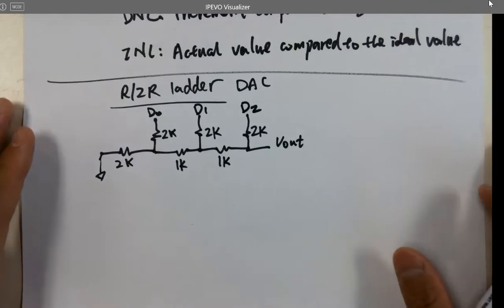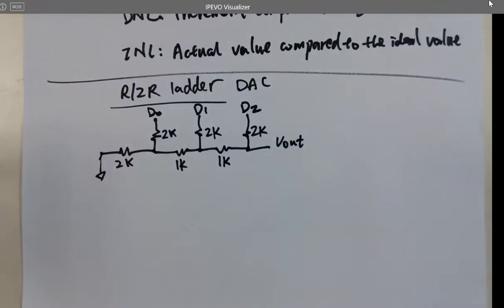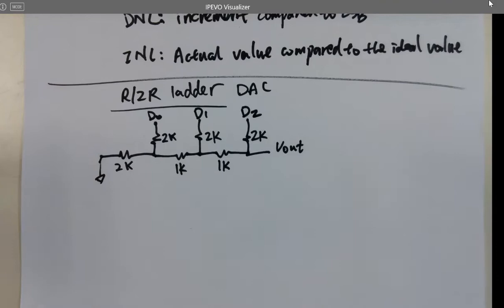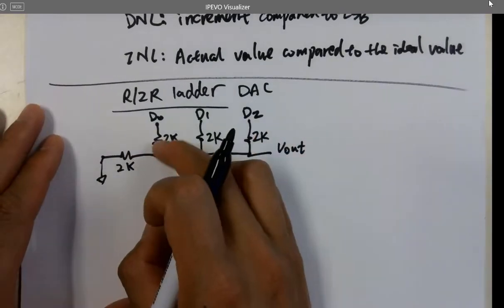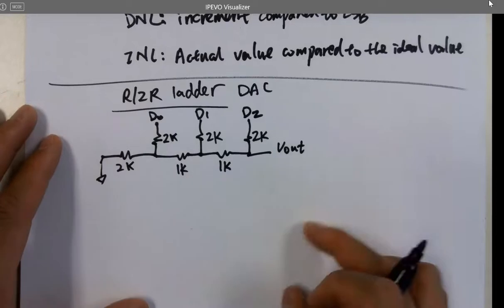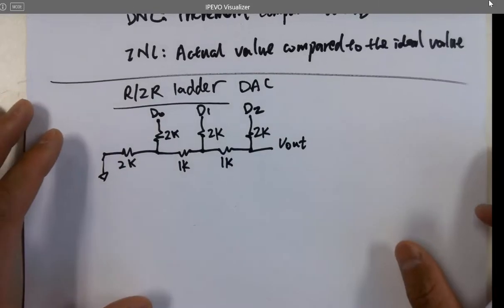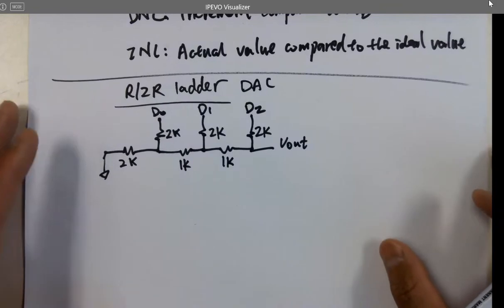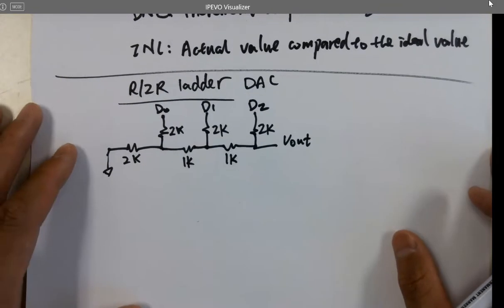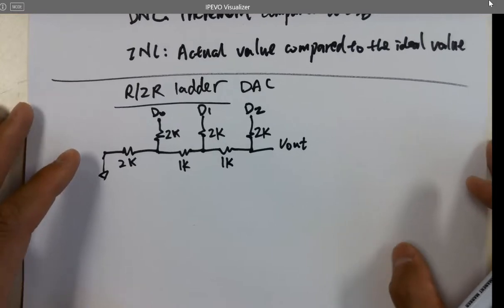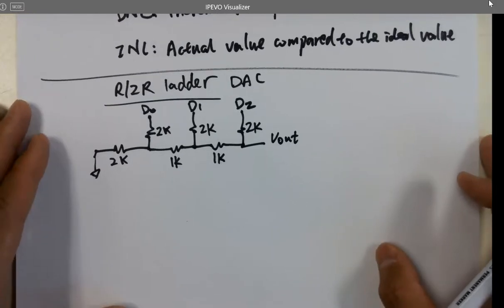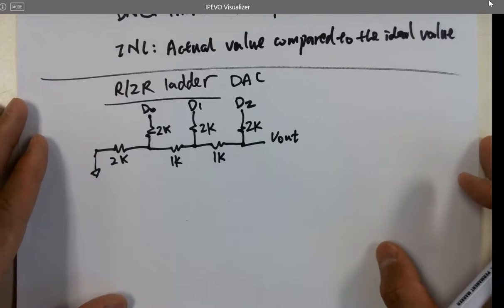That's a DAC. And we used this R2R ladder in the ADC we taped out last senior summer. It consumes a lot of power because of the resistors constantly conducting static currents. So that's why it's not a really ideal design. We're trying to replace it with a C2C type of DAC. So now you can understand why we had to cover Thevenin and superposition in the first week, because this is how you analyze the circuit.